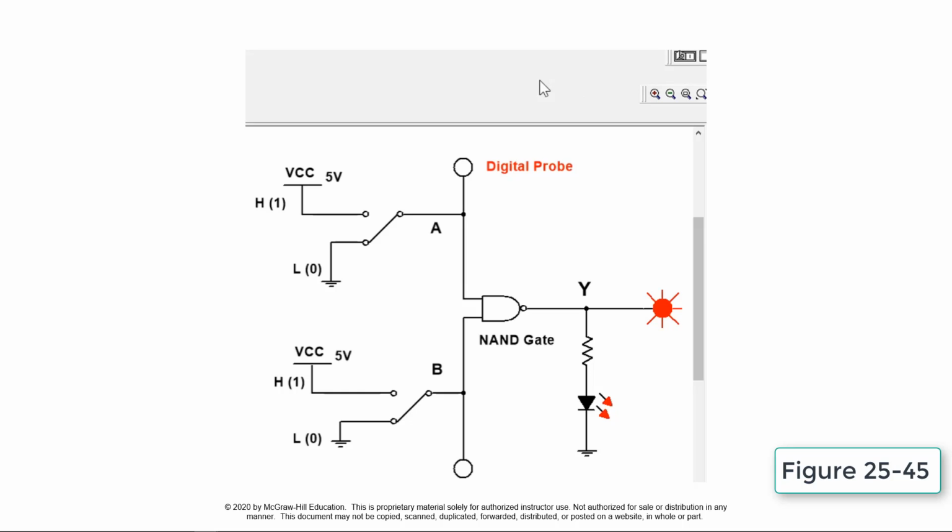This circuit simulates the operation of a NAND gate. An AND gate with an inverted output is called a NAND gate and operates as an AND gate followed by a NOT gate. The NOT function connected at the output of an AND gate will invert the normal output result. The basic rules that apply to a NAND gate are: if all inputs are 1, the output will be a 0. If any input is 0, the output will be 1. The simulation is operated to confirm this function.